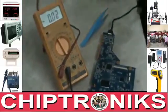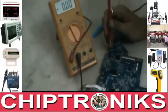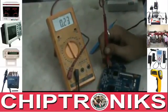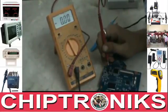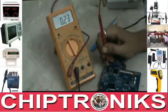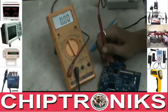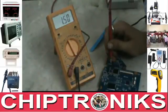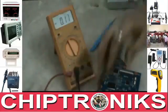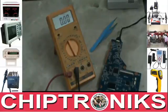Voltages first. What was the difference after doing programming? Yeah, here before programming, we got 0, nothing, on pin number 5 data. Let's check pin number 6, same voltage, 1.4, and let's see pin number 2. Yeah, here we get 1.5 volt. Before BIOS programming, here we got 3.3 volts, but after BIOS programming, here we get 1.5 volt. Now let's see what was the change on our oscilloscope.